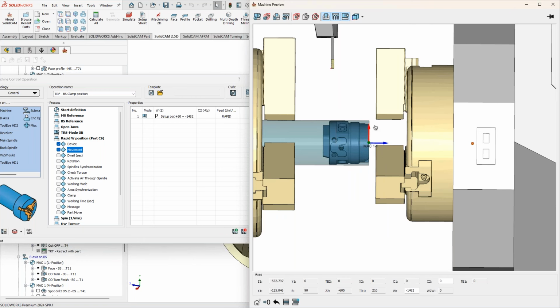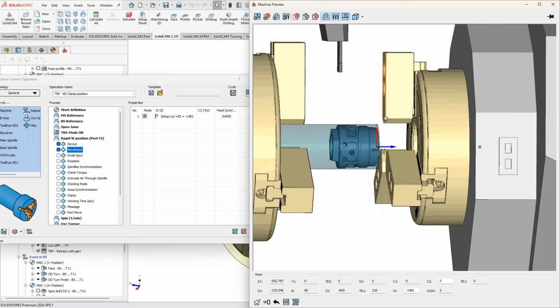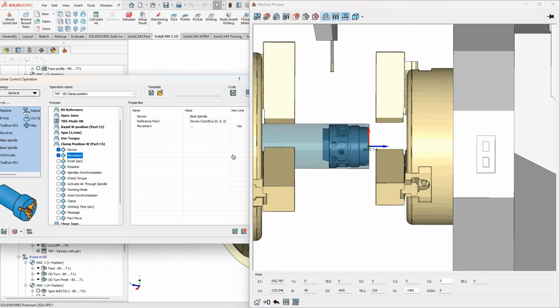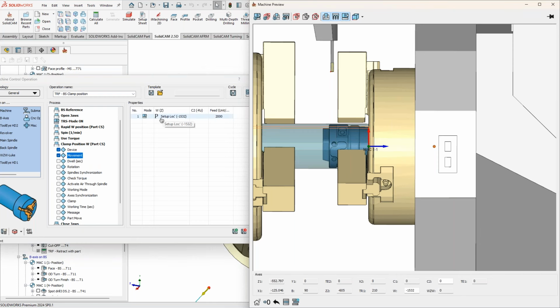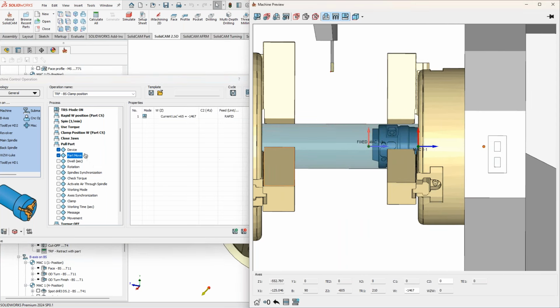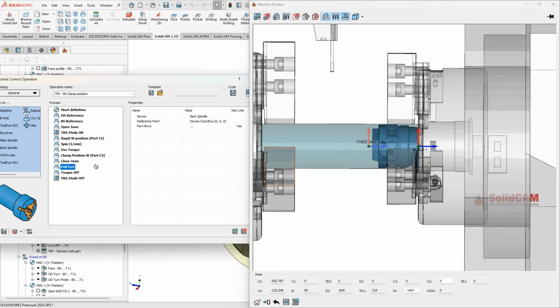But if you want to be more accurate, you can put your reference point or point of interest on the chuck and use the part coordinate input for it. Today, SolidCAM can support both. So I have here the rapid preposition. I have my clamp position, and also I have my tool part position. So let's see how this works now when I do have my shifting coordinate system.